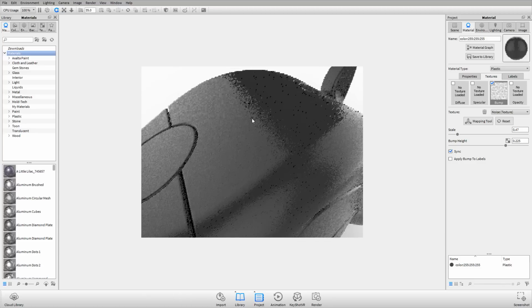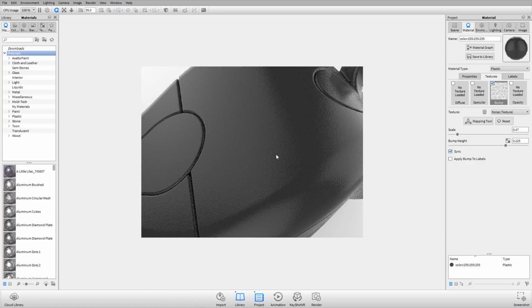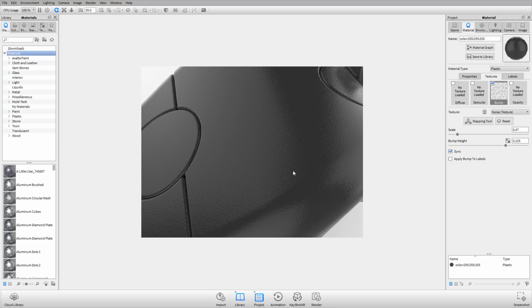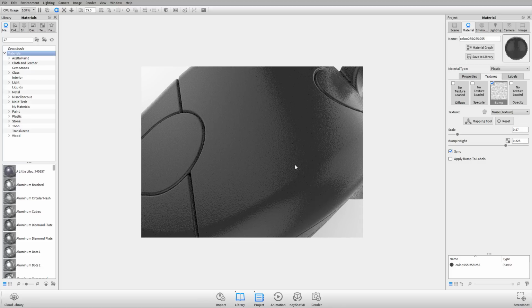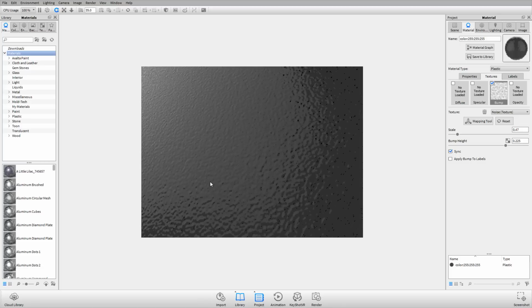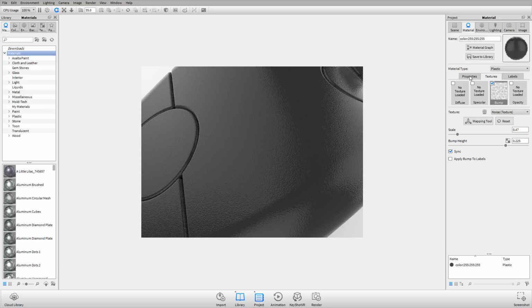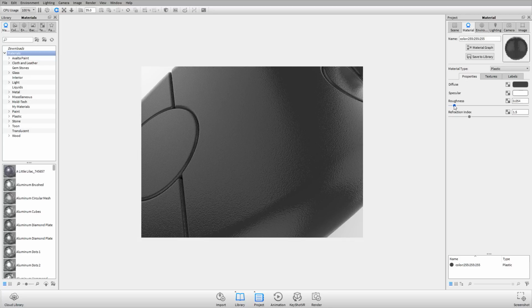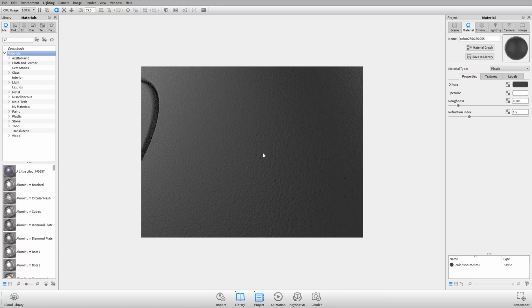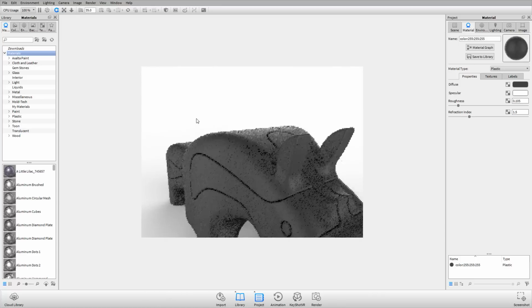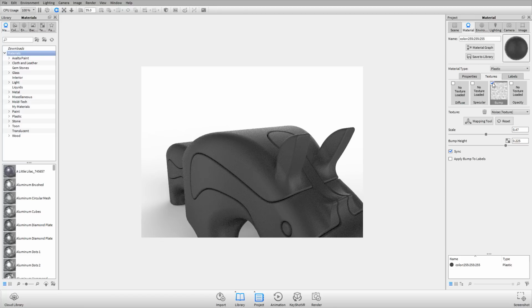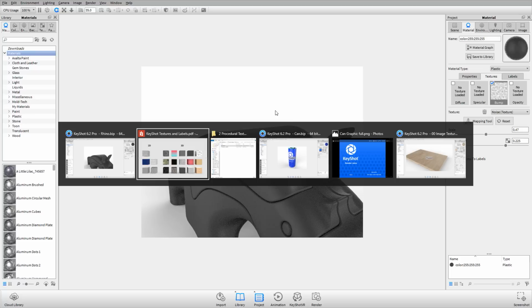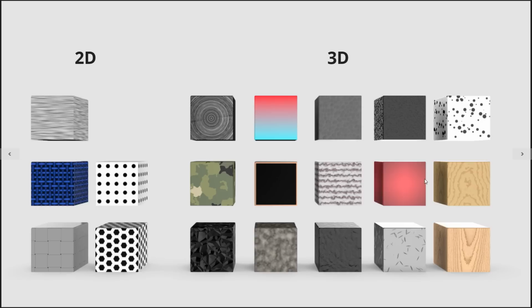And that was also some feedback that I read in the sign-up sheet. Adding something like a noise texture to the bump will allow you to add in some really nice fine textures. And then if I throw in some roughness, that will randomize those reflections a little bit more. But now we've got a really, really nice finish on this surface, again, because I'm using that procedural bump texture, which really adds a lot to it. So that's another procedural texture that we can use.